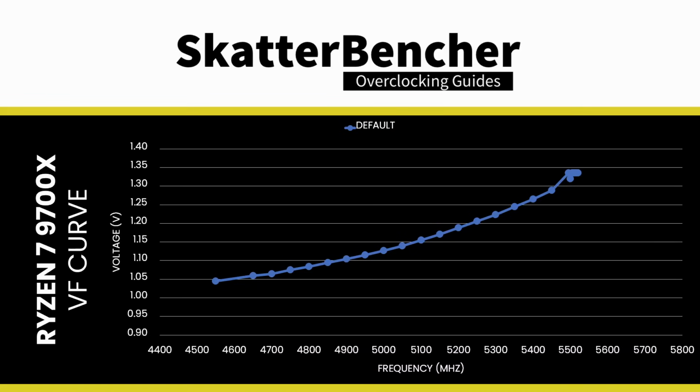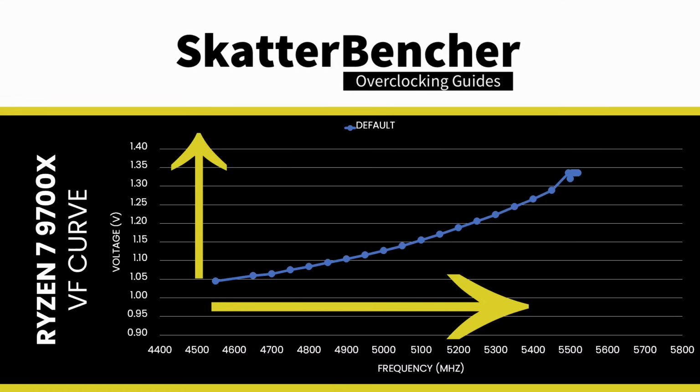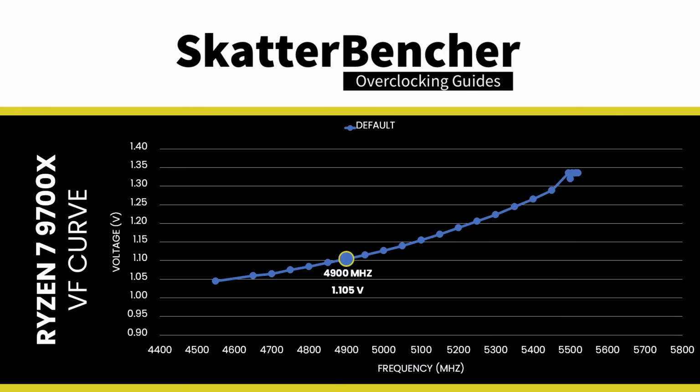We can immediately make a simple and redundant observation. The higher the frequency, the more voltage is required. For example, we only need 1.1 volt for a frequency of about 4.9 GHz. However, we need over 1.3 volt for a frequency of more than 5.5 GHz. We also notice that the maximum allowed voltage is 1.35 volt when all cores are active.